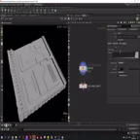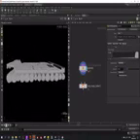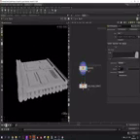This tool also makes high poly and low poly, so we can bake the results that we have. So let's say I want to see my low poly, then we switch to the low poly view, and a few moments later we will have the low poly. There are also a few settings, like a ramp control, which is used to extrude some parts of the panel, some high poly quality. We can say what the poly count should be, and also include some cleanup methods to remove some more polys if you would like to.